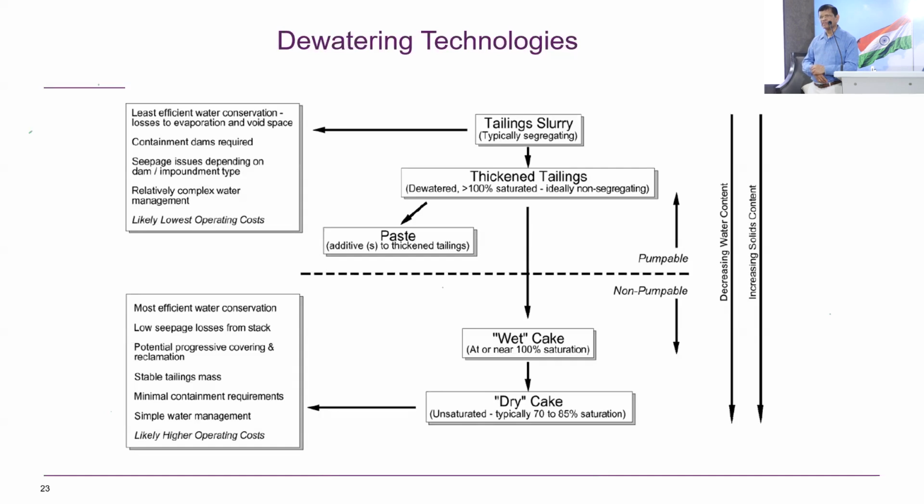Because in some bridges we put the reinforcement itself in the soil and then compact it layer by layer. The soil nailing. Now, in the case of tailings, it is difficult to do that because it's already developed slopes. So the reinforcement is different. You have to flatten the slope, you have to dewater the slope, you have to put some berms. These kinds of measures you have to take.